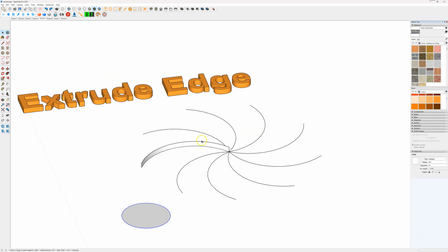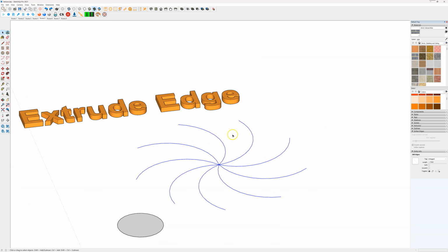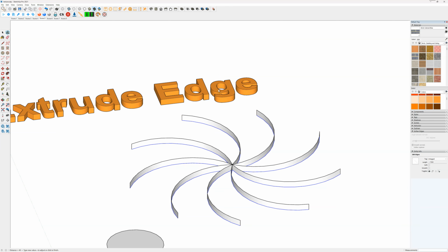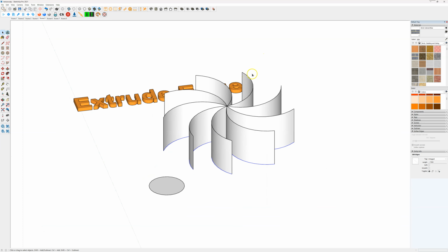So let's do a multiple selection now of all of these edges. Click extrude, and I can click up the ways, reference a height, or type height in. So I can just go here and then type 400, press enter, and it will change it to that height. You can actually extrude again and say I want to split this, so I can go up and type in 200, so I can half it. So it's half now. You can't see it because it's hidden geometry.